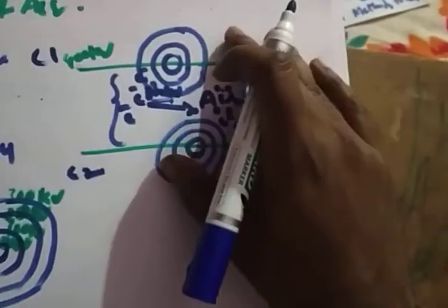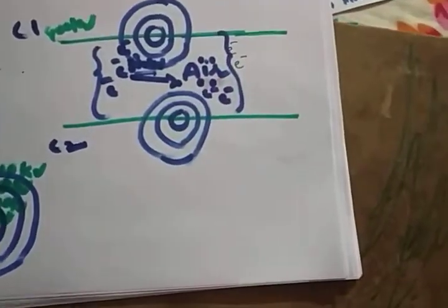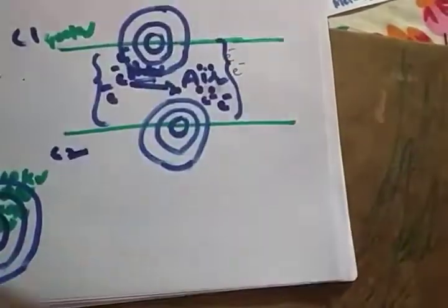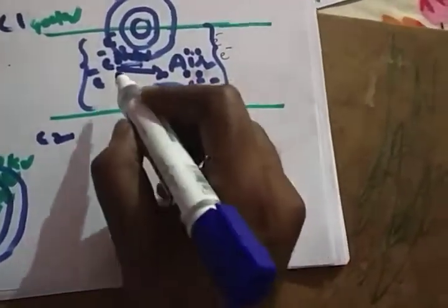But when you develop high voltage on the surface of the conductor, you get maximum stress. That means the electrons near the surface which jump into the air medium, the velocity of the electrons will increase, and the force will increase.